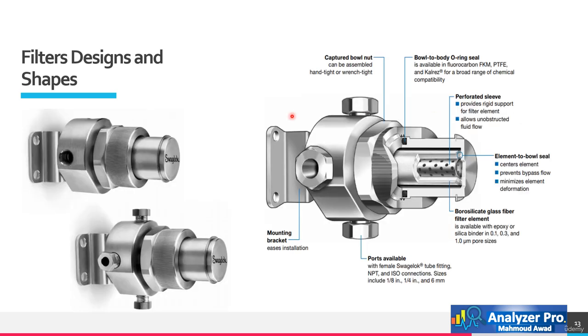Now we will see different filter designs and shapes from Swagelok Company. We can see here the filter mounting brackets, the inlet and outlet ports, and the nut that is used to open the filter housing and clean or replace the filter element. We can also see the filter element itself and the perforated sleeve that provides support for the filter element.